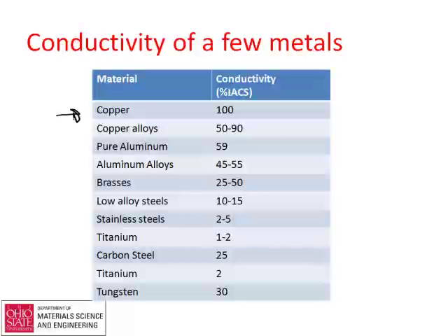Commonly, for household wiring and all that, we make our conductors out of copper. This is a conductivity of 100. It's our baseline. There are some materials like silver, which isn't shown on the list here, that have a little bit higher conductivity, something like 103 or 104 on this scale. And these numbers show how conductivity compares as a fraction of the conductivity of copper.